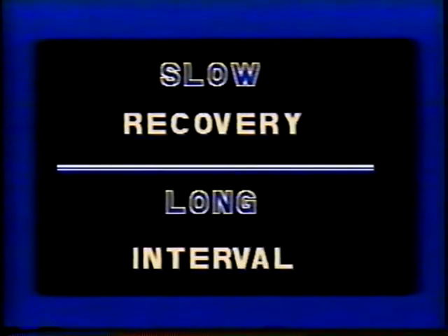The slower the response time of the system to corrective action, the longer the repeat time setting needs to be. If a system is undersized, it will take longer to recover from a load change. Therefore, the timing of the integral relay should be set to a longer interval. If the integral relay is set too fast, it will overshoot its set point in both directions. These oscillations are called hunting. Hunting can also be caused by a throttling range that is set too narrow.